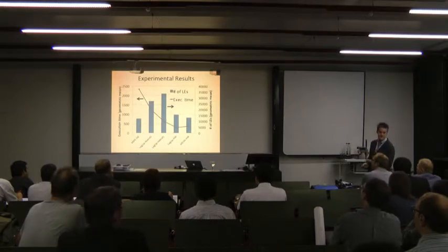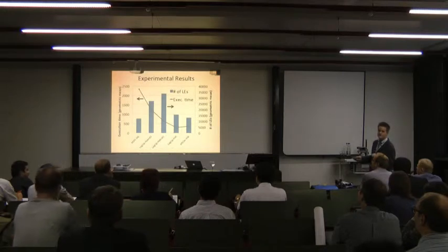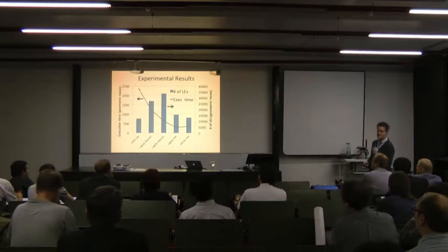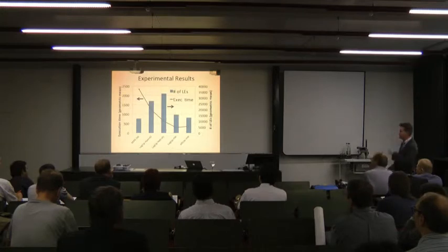This is for the CHStone circuits geometrically. On the right axis, you see their area, number of logic elements in Cyclone II, which a logic element in Cyclone II is a 4-LUT flip-flop pair. These two middle bars, they're very high bumps because they contain the MIPS and accelerators. These rightmost bumps, there's no MIPS, just completely pure hardware, so they call that.